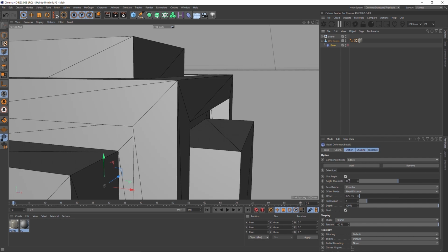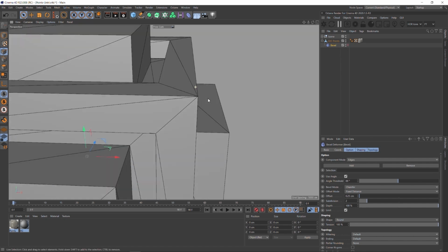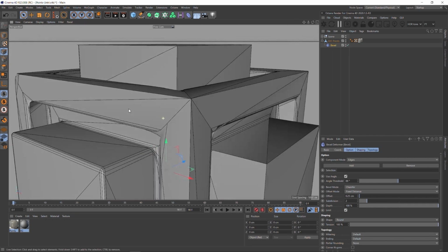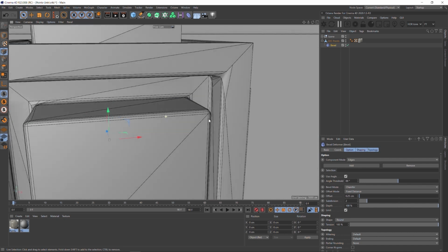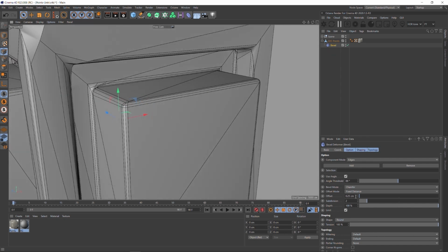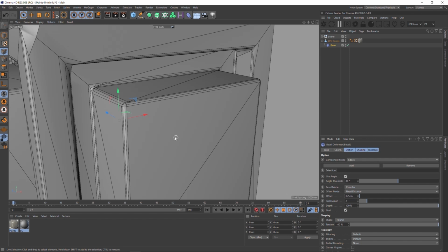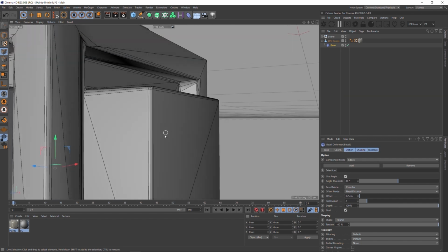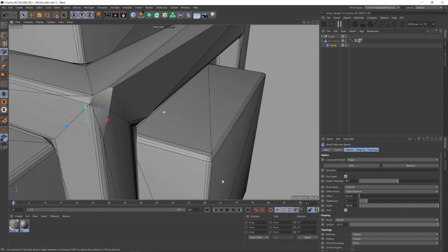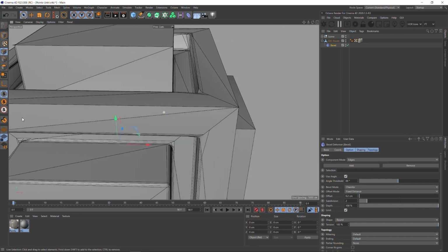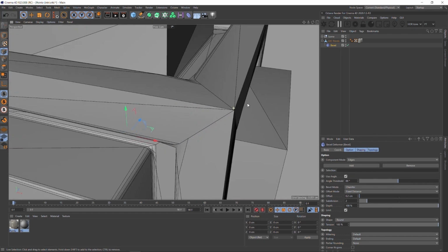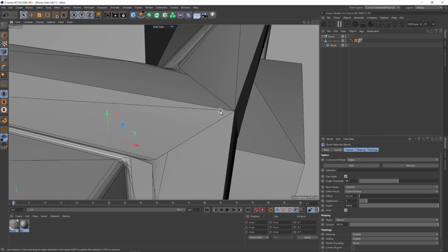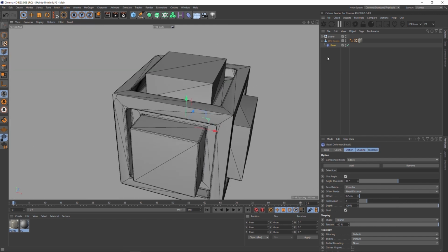And you can go through the help and learn a little bit more about that if you're not familiar with it. But this is important because you want rounded edges. Nothing in this world has a sharp corner. So let's turn on our bevel. And we can see that in some spots we're getting the bevel. And let me change this to 0.2. In some spots we're getting a decent rounding on the edges, but on other spots it's just falling apart. And that is a direct result of points not being connected and the mesh not being completely closed off.